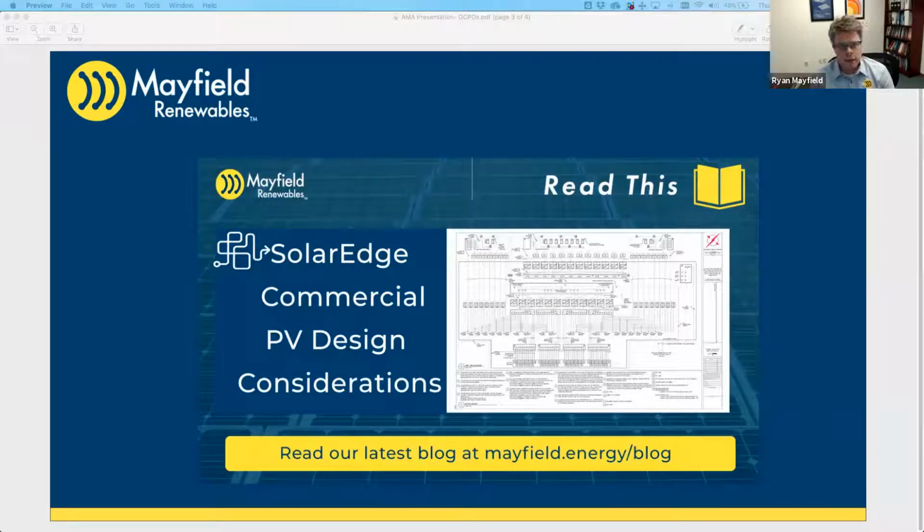So I would highly suggest doing that, just because otherwise, if you're going to be ultra conservative, which will be some people's method, or their default way of doing this, using the highest gain percentage and then applying all of our traditional code derates on top of that, you're potentially going to have relatively high overcurrent devices and high conductor sizes for a situation that may not actually come into play. So that would definitely be my recommendation, using either one of those, Sandia or SAM.